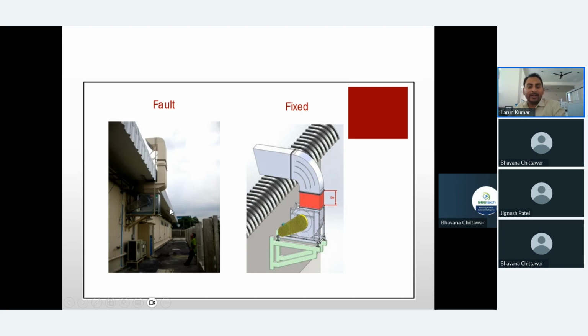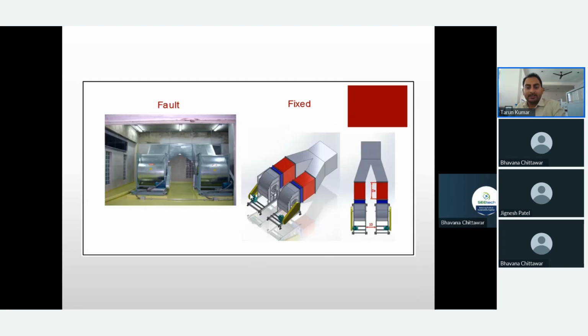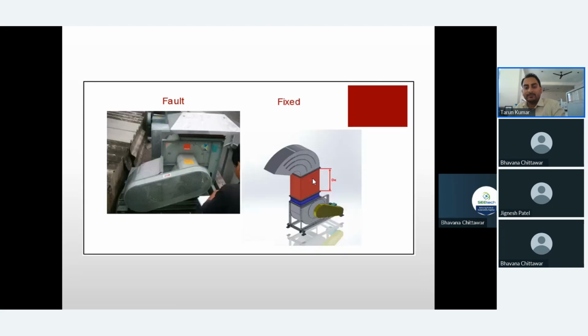They would have taken that fan a little bit outside, and they would have taken this kind of arrangement, which will avoid the bend as well as the back pressure over the fan. Again, you can see the example of the branches. When you are combining two fans in a single duct, again you have to go with some flexible connection, and when you are putting the common duct plenum, you have to go for a certain distance of straight duct, then go for the branches.